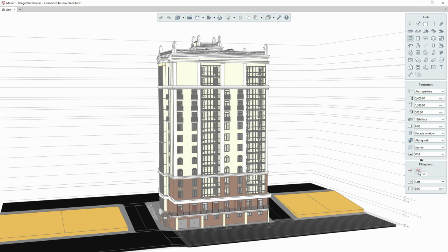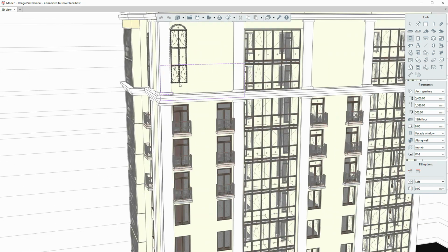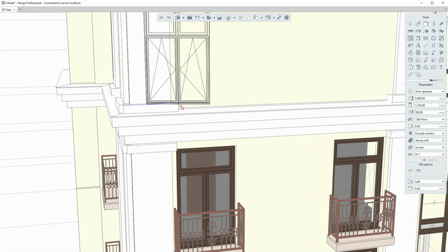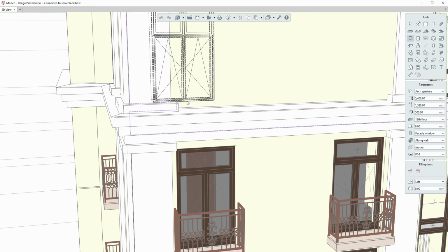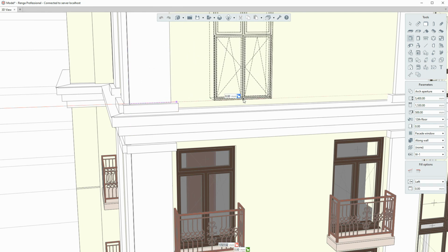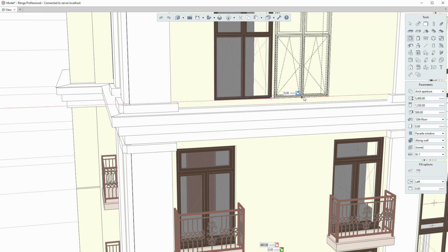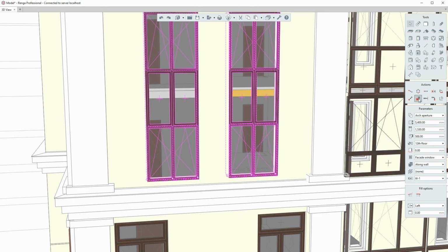If the window style is defined, we can specify the following parameters. Presence of a window sill. Presence of a window outward sill. Window orientation. Window depth. Parameters may be modified both in the construction and editing processes. Press Enter to fix the parameter values. Finally, select where to install the window in the wall. All snaps and accurate construction are available for window construction.